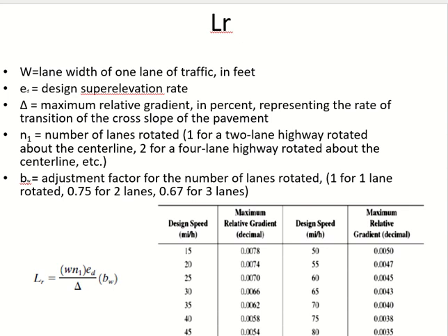If they asked me to design a curve, we did one example yesterday, I'll take this maximum value and design my curve. Which curve? Circular curve. Am I designing a circular curve? No. Circular curve is already there. I found the radius for the curve and the degree of curvature is already given. So now I need to find out what was the exact super elevation taken for the design, which could be 6%, but it could be something less as well.